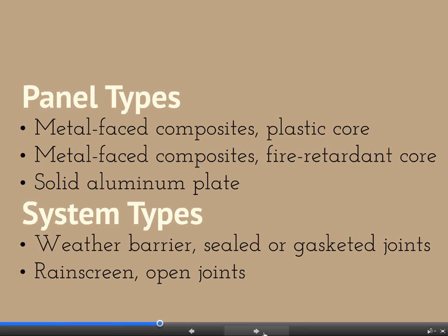To maybe help move us out of this whole issue with NFPA 285, but it also does not give you as good an R value as the other insulations that are available. And of course, polyiso, many of those systems have a shiny foil surface on the outer side, although some manufacturers make it with one facing that's less reflective. And then of course our friends that make XPS tend to make it in sky blue and bright pink. So that is something. That could just be for interesting contrast.